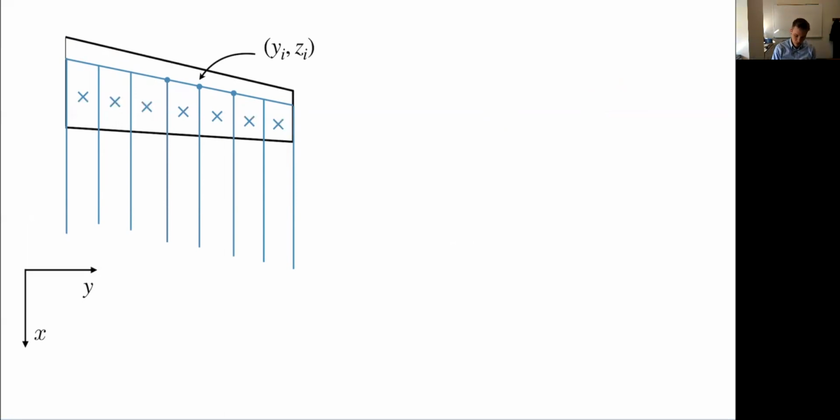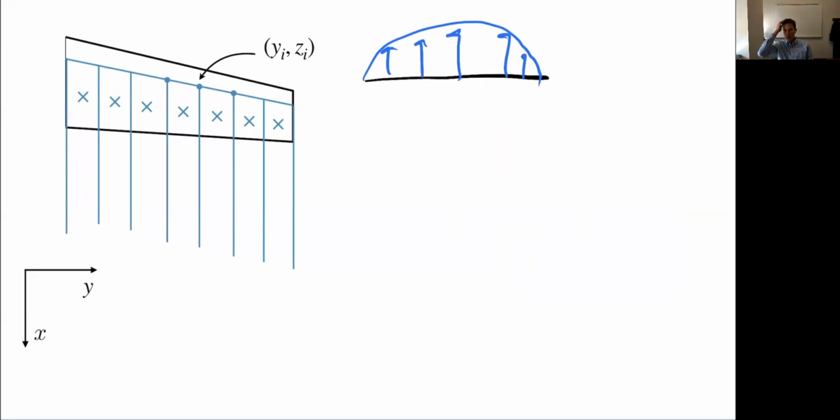As we've seen, what we're really trying to look at is things like, here's the back view of my wing. I want to know what that lift distribution looks like. As we've seen, that's going to affect obviously my lift, but also my induced drag. And so that's something I couldn't capture with my airfoil method, so I want to be able to capture this on my wing.